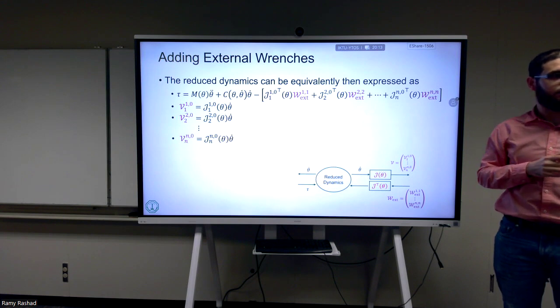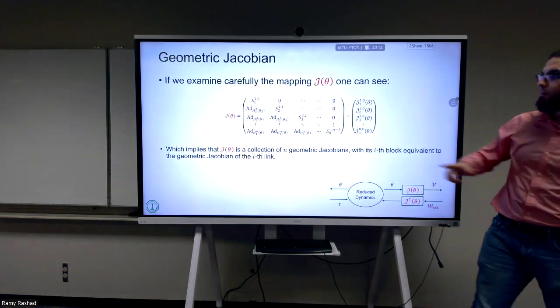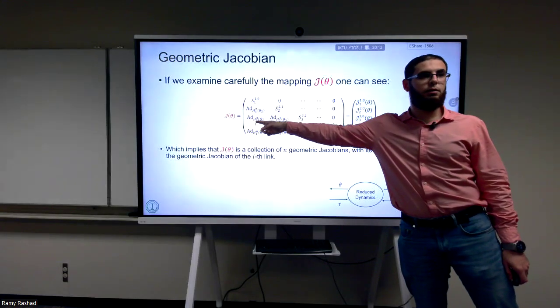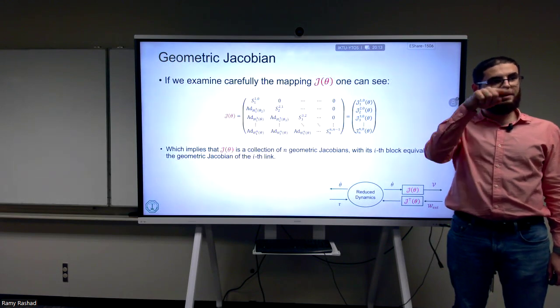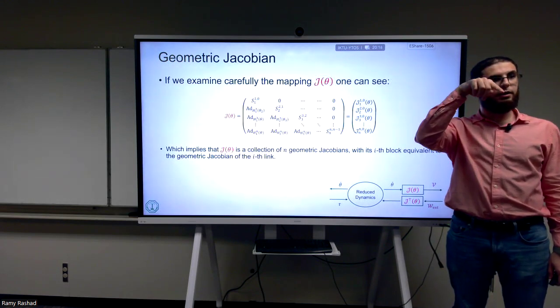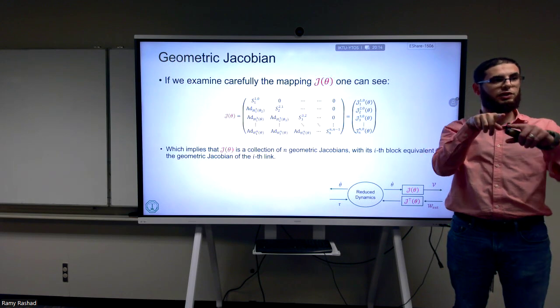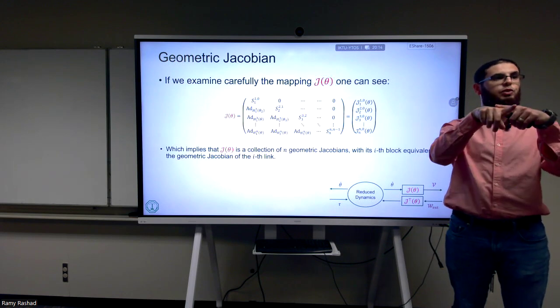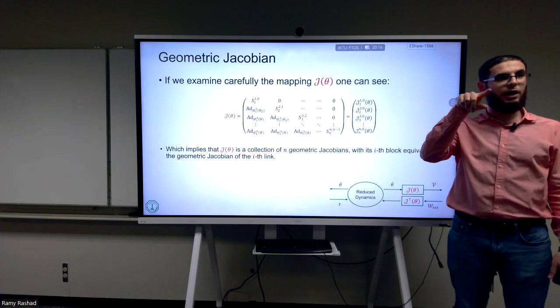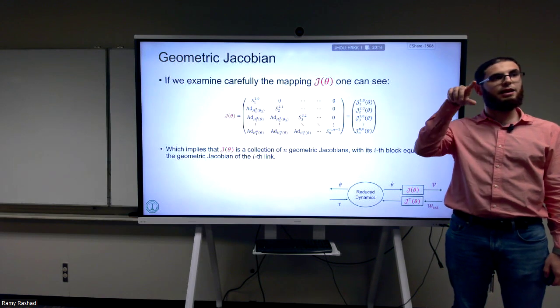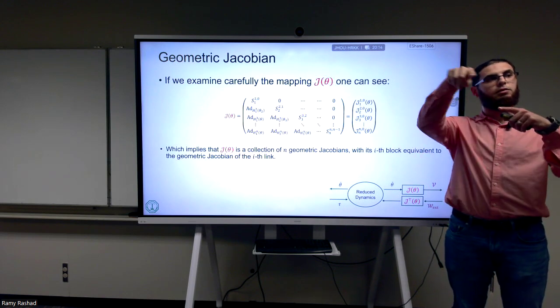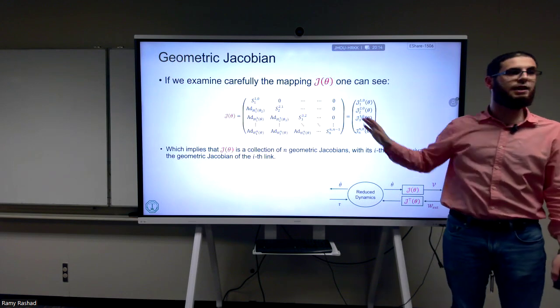The Jacobian here is a map between theta dot and that joint. That joint has a distance, and distance with a tilde, right? The psi tilde, what does it do? It transforms a force into a torque, because it's the cross product. So when you multiply the psi tilde by a force, this is precisely the cross product of the psi with the force, which gives you a torque in the end. And it takes care of all of that.